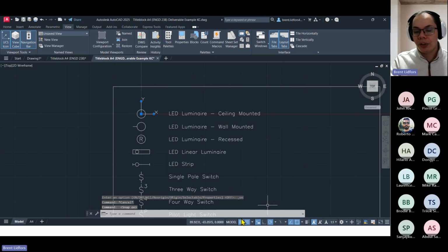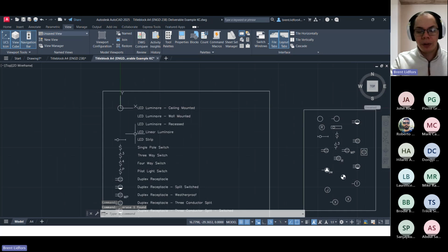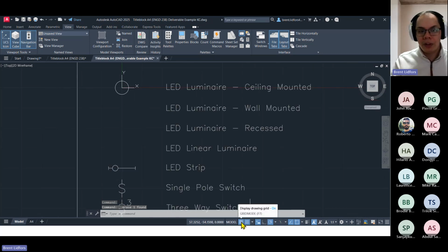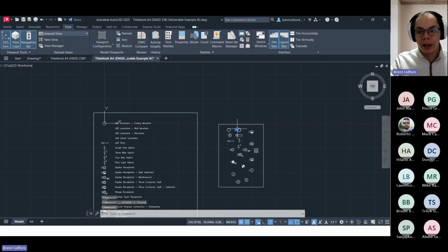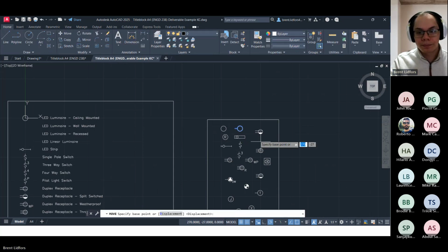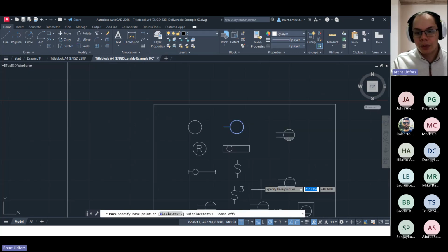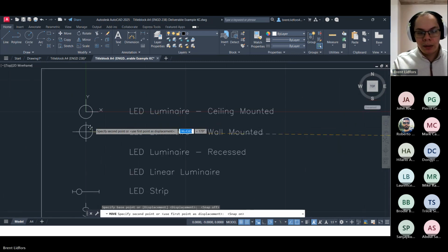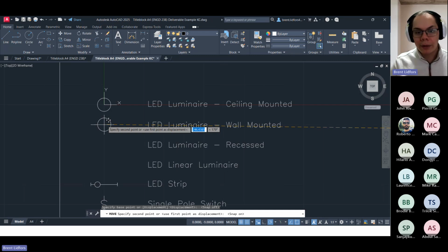So when I go into center snap and move these objects around, like if I didn't have these symbols here and I needed to place them, since I have grid set to 9 for the spacing and I have snap on, I can take the next symbol and grab it by its center point. Oh, I gotta turn off snap. Grab it by its center point, turn on my grid snap, and then just plop it along that grid. Since my grid spacing is set and I'm snapped to grid, this spacing should be exactly what I set it to, and it should be perfectly in line.